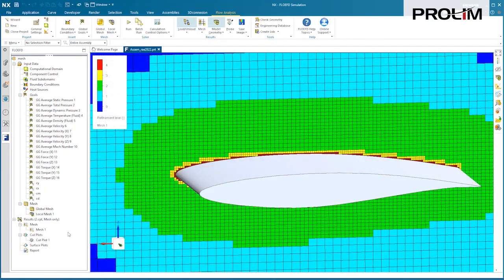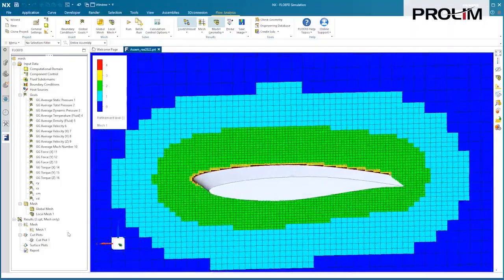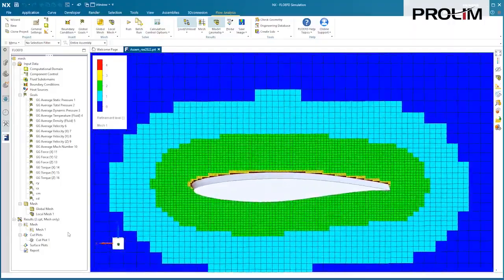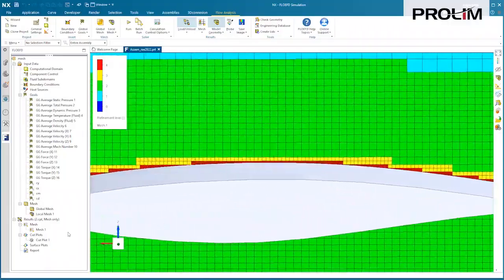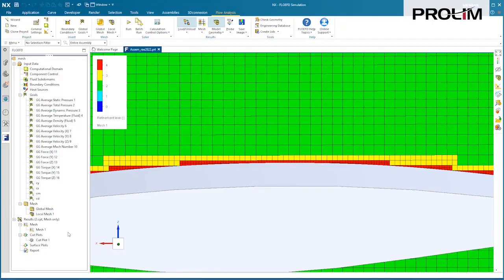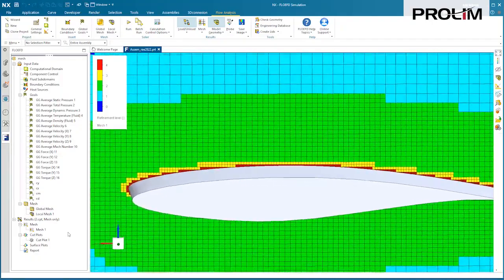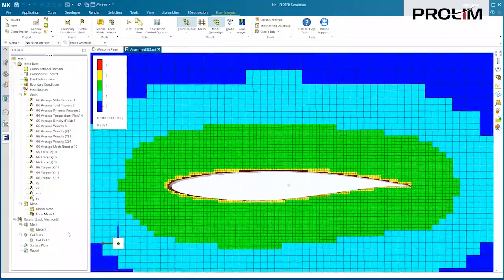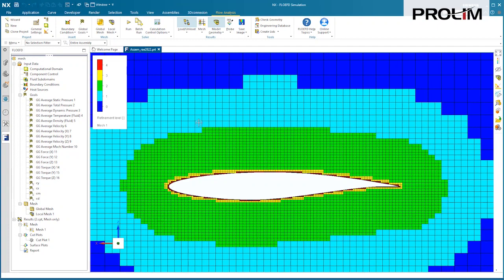Let's now have a look at the mesh created. The first is the default mesh using the base settings, plus our local initial mesh and has approximately 46,000 cells. The mesh system in Simcenter FLOEFD works using levels, which are shown here colored from blue to red. The base mesh is referred to as level 0 octree. Mesh refining means that a single cell is then split into 8 cells to go to the next level up.